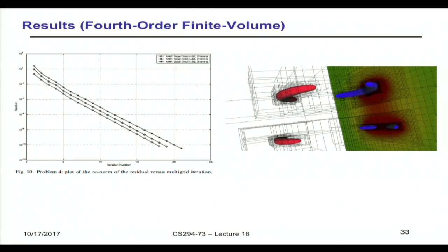Now, because this is called vorticity stream function, but this particular problem is a Poisson problem, you're going to get textbook convergence. But it's a 4th order finite volume method. So again, you have to be concerned about those higher order interpolants and what does your relaxation scheme look like, and am I getting all the high frequency content and things like that.